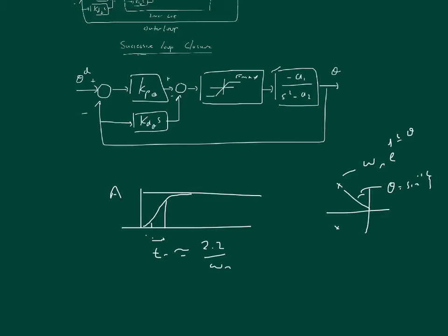My point here is that if you apply a step of size 2A, what will be the rise time? And the answer is that it's exactly the same. So the 10% to 90% rise time is exactly the same. So the pole location gives the rise time for any step. However, the magnitude of the force that will be required to achieve that step will, of course, increase. So if the force is limited, then that limits the rise time that you can achieve for a given step.